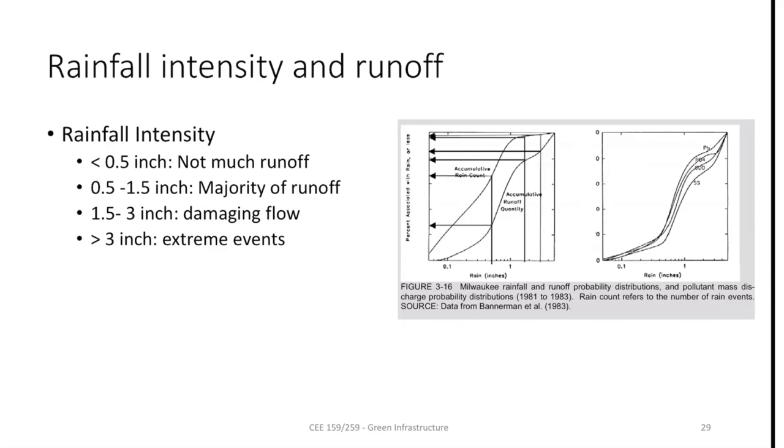Rainfall intensity itself, the unit of measurement is like length over time, right? Yes. So I think in this context, it's mostly on a depth: at any single rainfall event, how much rainfall happens. So let's say this 3 inch rainfall happens in 30 minutes. It's pretty bad already, right? So that 3 inch rainfall continuously happening for 2 hours is also bad because this much water is being dumped. So this is mostly a cumulative depth in that one rainfall event in this particular case, even though I wrote rainfall intensity here.